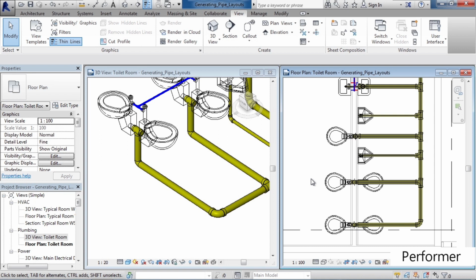We also talked about looking at multiple windows, tiling these views so you could look at two different views of the same thing at once. We routed pipes from an existing fitting by right-clicking on the drag handle and then choosing Add Pipe. And we also looked at the pipe routing settings, where we could control what type of T's, what type of elbows, or what type of pipes are actually being applied to our pipe system as we route our pipes.